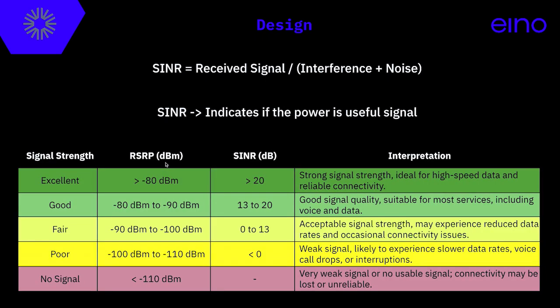In terms of how good is good, similar to RSSI in Wi-Fi, if you're about minus 80 dBm, 20 SINR, that's quite great. And we could go as low as minus 105 generally and positive SINRs, and that works for most of the use cases, depending on the device, of course. Minus 100, you could be safe there, and that's the consideration you need to have.